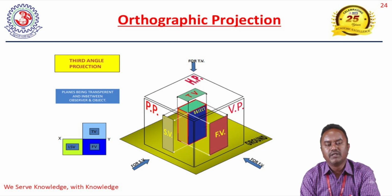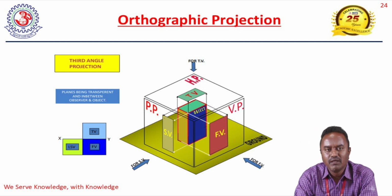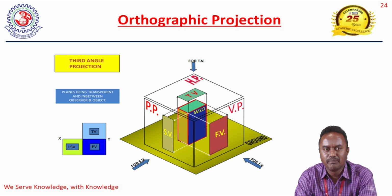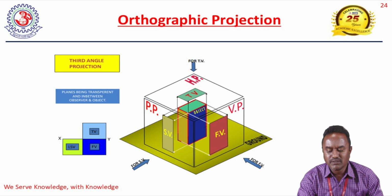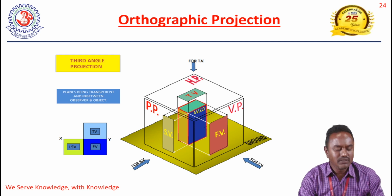So when we come to the detail about the first quadrant, when any object is placed above HP in front of VP, that comes under first angle projection. So in first angle projection, the front view is above the XY line and the top view is below the XY line. Just a reverse of the first quadrant is actually the third quadrant. In the third quadrant, below HP and behind VP, the front view is coming below the XY line and the top view is coming above the XY line. This is the difference between the first and the third angle projections. So the third angle projection is the reverse of the first quadrant. That will be explained.